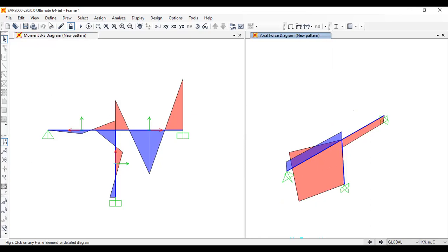One good thing is whether your FEM model, this finite element model, the analytical or mathematical model, represents the actual conditions, materials, loading, everything, the assumptions we made. If so, our calculations should be almost identical, because the assumptions we made are represented in the FE model as well. So that's how we interpret the results. Modeling is not the case, interpreting results is. That's important. You have to convince your client or someone else why this kind of force is there.